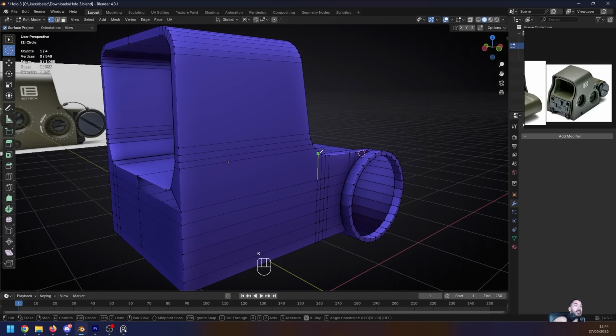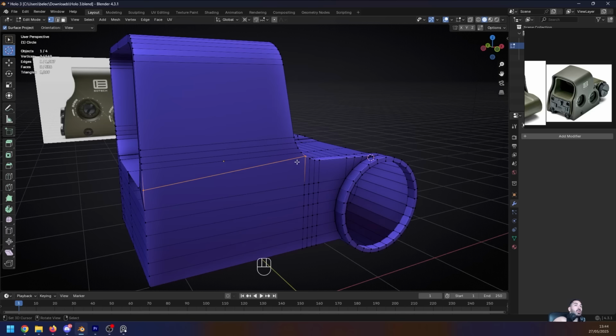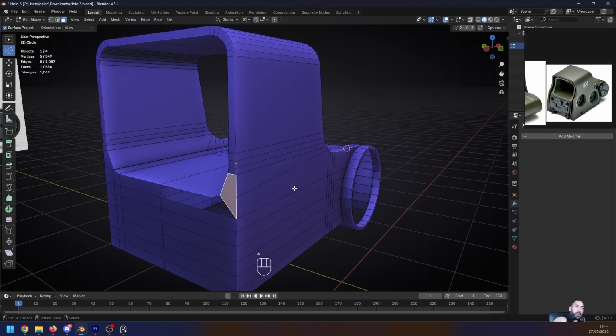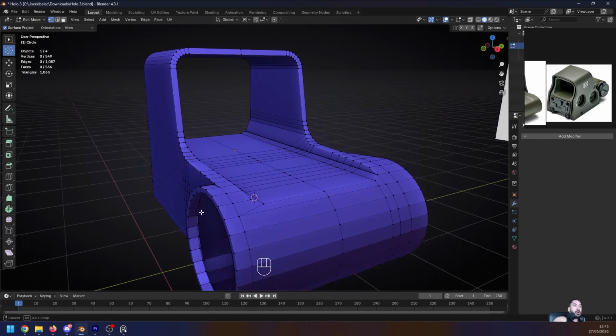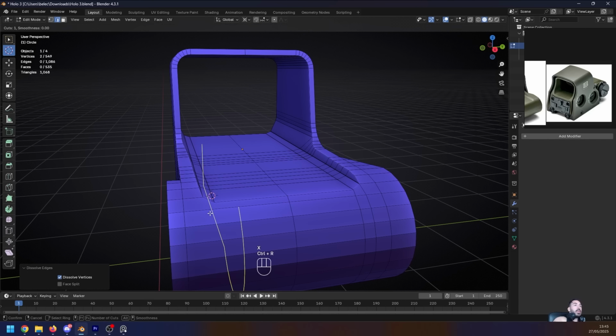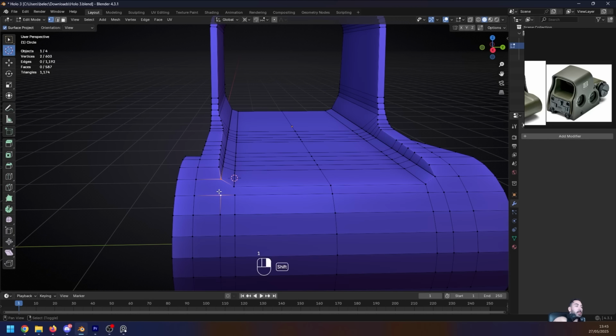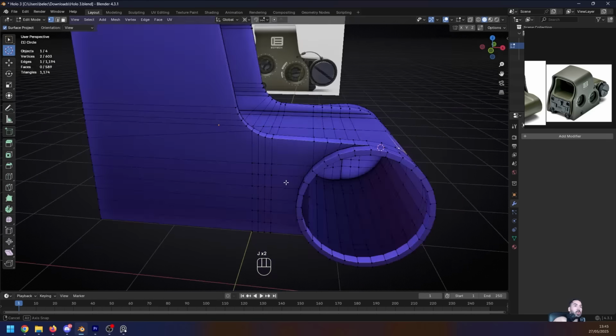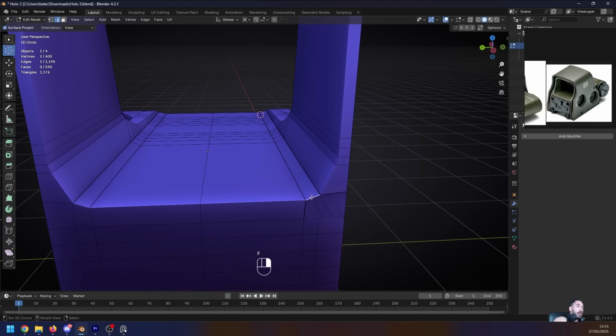We gotta do the same thing over here on the other side, so I'm just gonna do that one more time in case you couldn't follow. First I add a knife cut over here through this end gone, then I delete this face and I reconnect this. Now I need 2 more loop cuts down here, but first I need to get rid of this diagonal edge. That way I can create these 2 loop cuts, then I can join those loop cuts down here with J, and that allows me to connect everything in the back.